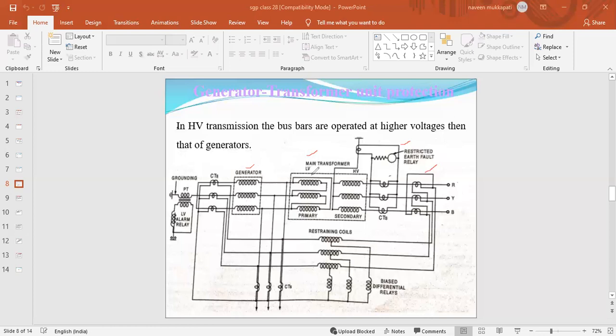Okay, these two protective systems protect against phase to phase faults and also phase to earth faults, some interturn faults, leakage of flux, and combined protection for leakage windings. All of that will be protected by using these differential protections. Okay, that's why first the generator unit is connected to the main transformer, and on both sides of this generator